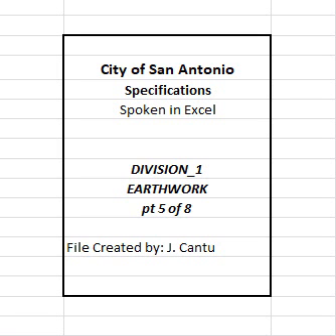F. Acceptance criteria. 1. Grade tolerances. A. Staged construction. Grade to within 0.1 foot in the cross-section and 0.1 foot in 16 feet measured longitudinally. B. Turnkey construction. Grade to within 1/2 inch in the cross-section and 1/2 inch in 16 feet measured longitudinally.